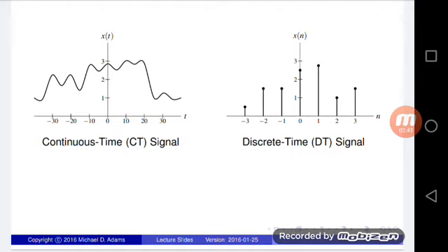But an electronic device receives the analog signal, and it must be converted into digital form. Analog to digital conversion internally includes three steps, not a direct conversion. First, the continuous time signal or analog signal is converted to a discrete signal.